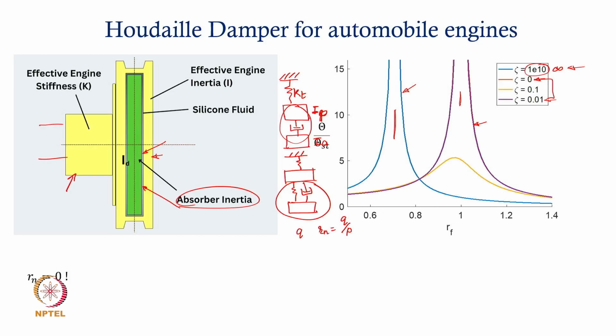With zero damping, it is sort of not being there at all, and then you have a higher frequency over there. Okay, what is the response for an intermediate damping case? 0.1, this is what you get, okay. And the way we saw in the previous case, we have a point, an interesting value of the force frequency ratio, where all the graphs irrespective of the damping pass.